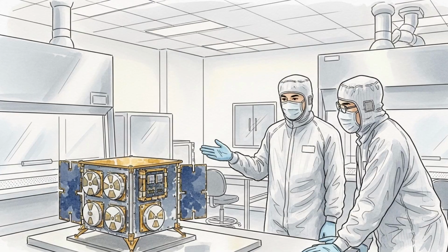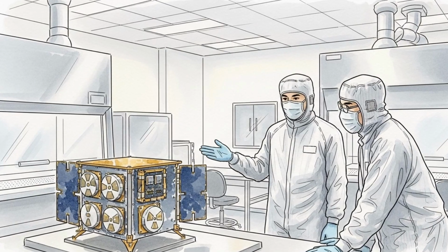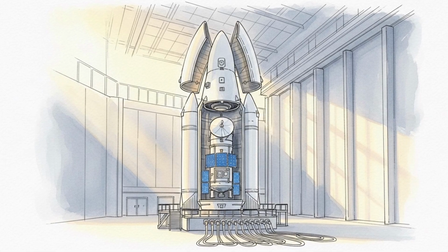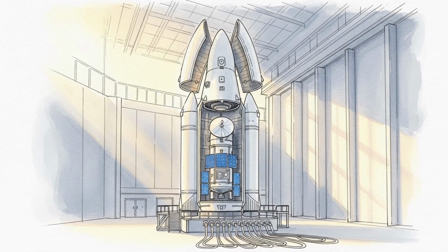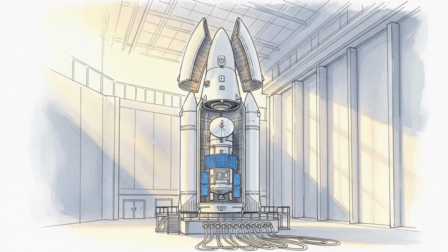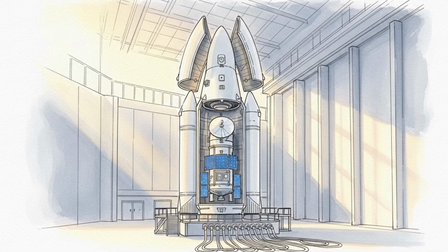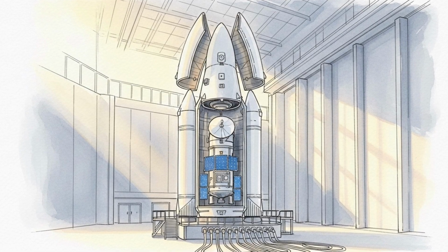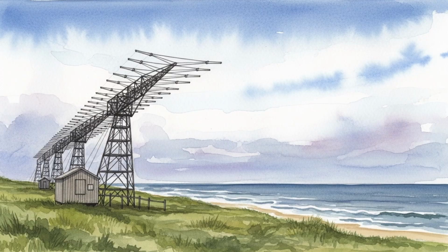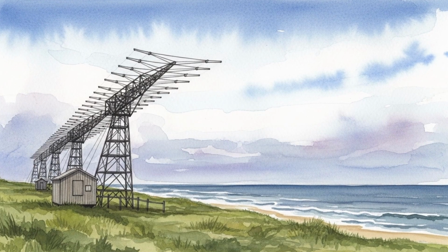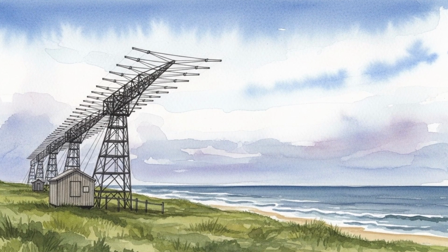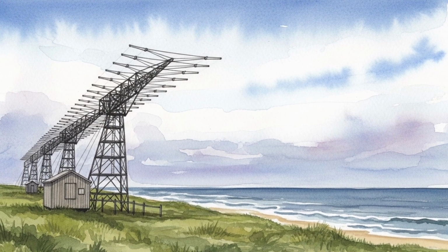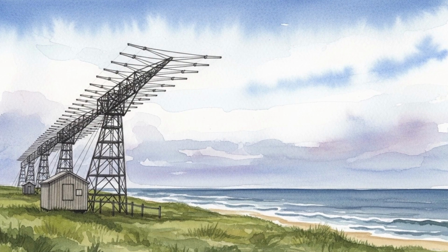In summary, space weather can remove high-frequency paths, degrade L-band and S-band satellite links, raise timing errors in networks that depend on satellite navigation, and create alarms in long-powered cable systems. Direct payload errors in fiber are rare. The main practical defenses are redundancy in frequency bands and paths, robust timing architectures that include holdover and terrestrial distribution, disciplined grounding and protection at stations, and rehearsed operating guides. These measures keep communication and internet services available or degrade them in a controlled way during strong solar storms.